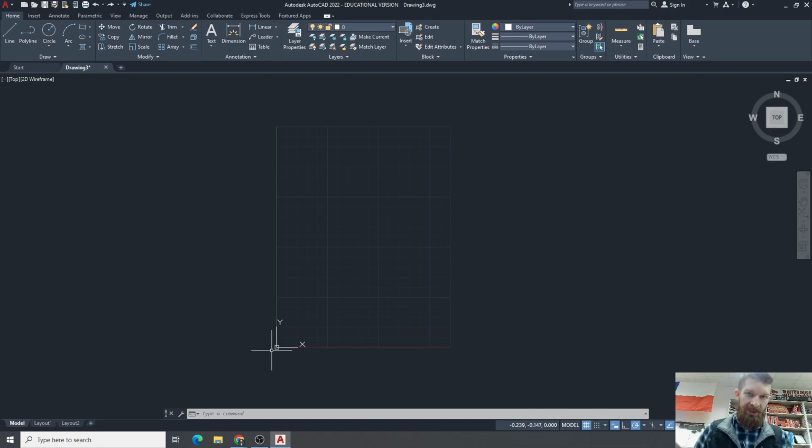Let's talk about drawing scale factor, DSF. Drawing scale factor, the definition is the proportion of the limits to the intended print or plot sheet size. That's the drawing scale factor, right? It's actually just your limits divided by the size of your sheet. DSF is equal to the limits that you put in divided by the sheet size.